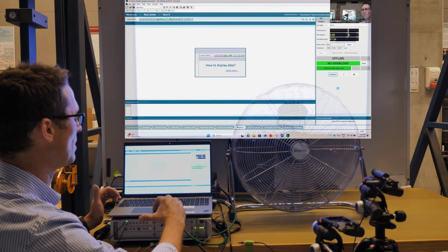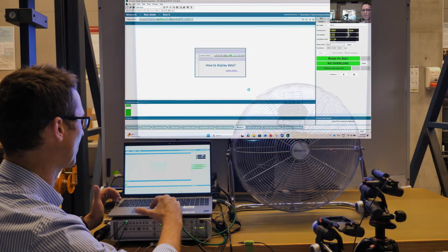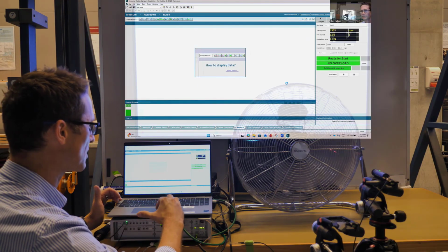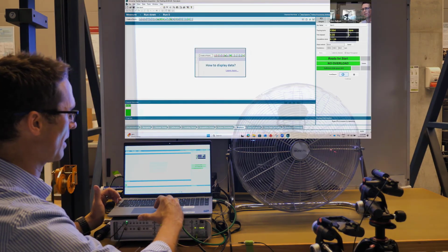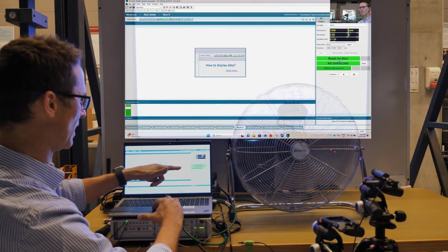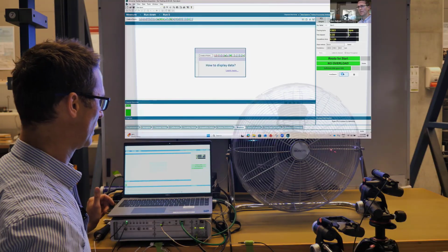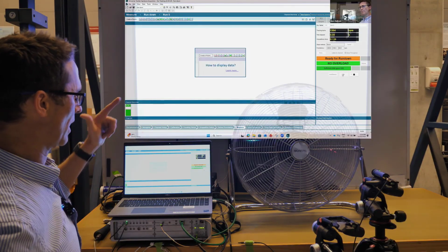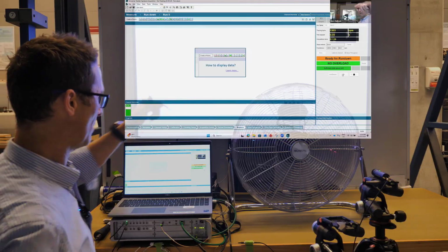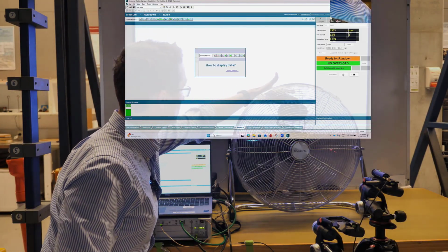spectra. So if I arm the measurement sheet, I haven't defined any particular display here, but I could create a display and populate that. Now I've armed the measure sheet. We're sitting here waiting to do a rundown from 1250 to 100 RPM in 50 RPM increments. So now we're sitting here armed and ready to start the acquisition, and if I press the stop button here